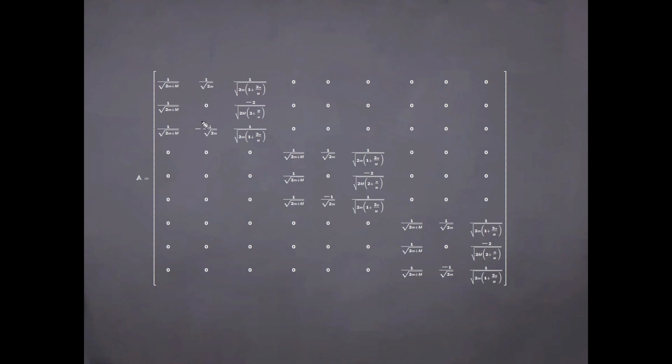One of them, this one, corresponds to the even vibration along the x-axis. These 2, so this one and this one, will correspond to the rotations about the y and z axis, and the last 3, this one will correspond to the odd x mode, and these will correspond to the odd y and z modes respectively.